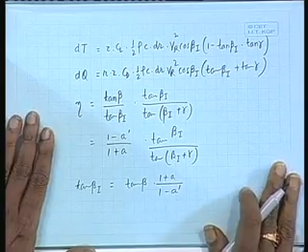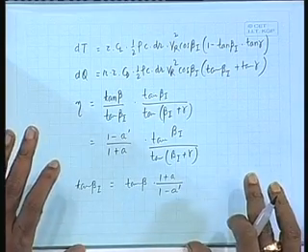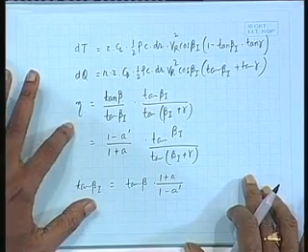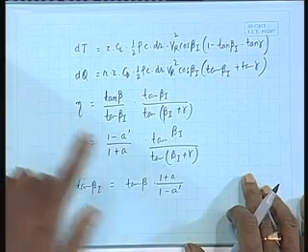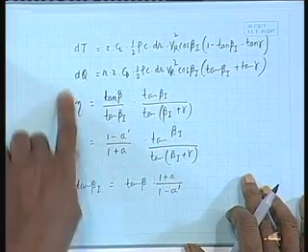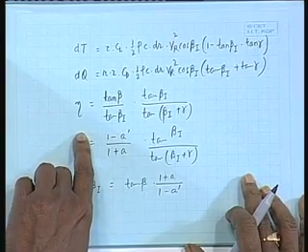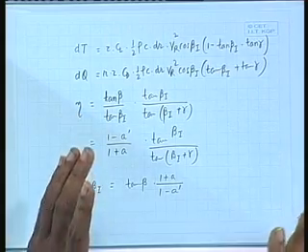This is the derivation we can get from the blade element theory. We can calculate the efficiency of an element. Now, if we assume that all the elements of the blade produce the same efficiency, then this will be the efficiency of the overall propeller. If we can design all the elements such that the efficiency of all elements is the same as this, then my overall propeller efficiency is also equal to this, isn't it?